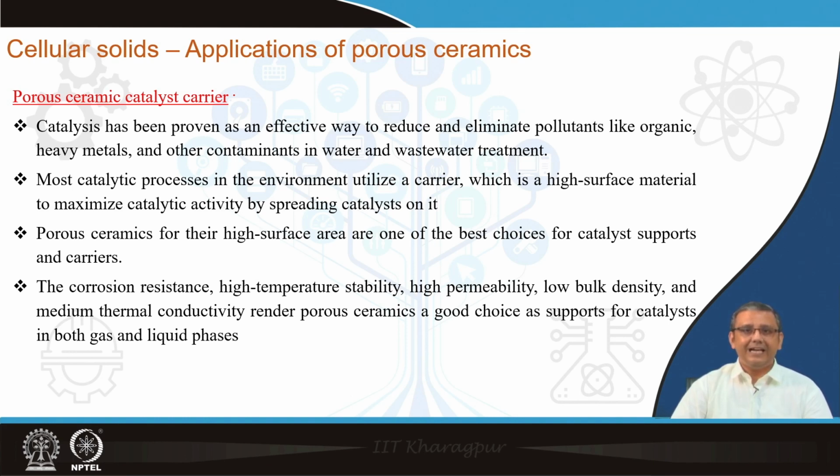Again, this catalyst carrier is used for many applications, like containing gaseous pollutants, and in these cases they also deal with pollutants like heavy metals and other contaminants in water or wastewater treatment. And again for these applications, porous ceramics with a very high amount of porosity, pore morphology and interpenetrating porosity can provide a very good material for catalyst carrier.